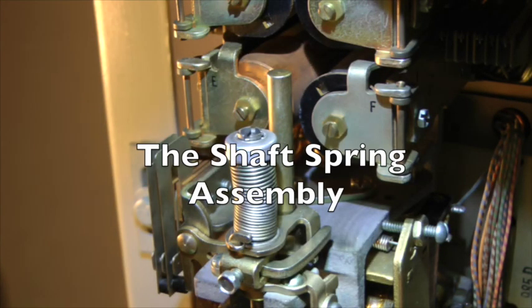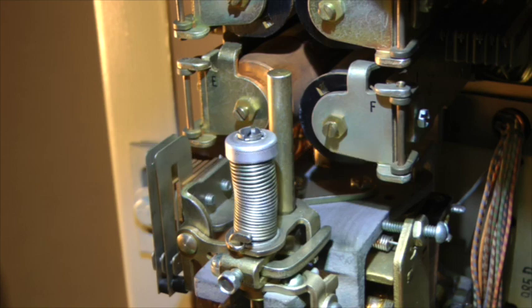Let's turn our attention now to the rest of the apparatus attached to the shaft. Starting at the top is the shaft spring assembly, which has a cap, a coil spring, and a shaft spring bracket. The purpose of this spring assembly is to provide the necessary force to return the shaft to its normal rotary position at the end of a call.